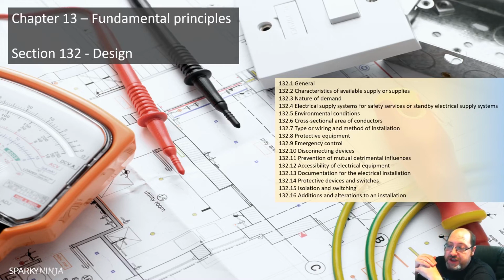The environmental conditions, we'll look at that in chapter 52 or through to appendix 5, but that will also give us information in regards to IP ratings, ingress protection and things like that. Also, it'll tell us about limiting temperatures of conductors and all that stuff. So the environmental conditions are very important. Also, with environmental conditions, we've got to consider things like capability of users and building structure.